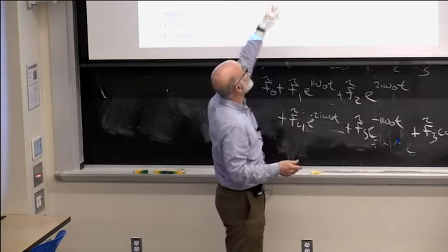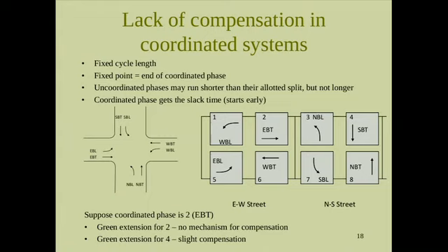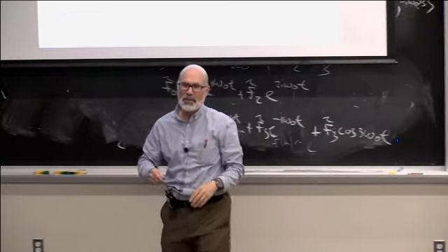That depends. Whichever one has more traffic, 1 or 5, that will stay green because it has detectors, while the other one gaps out. So maybe 5 gaps out first because it had less traffic. Then 6 becomes green along with 1. Eventually 1 gaps out. Now 6 is green along with 2. But then 6 and 2 have to end together, and then we have the same thing for the north-south street.